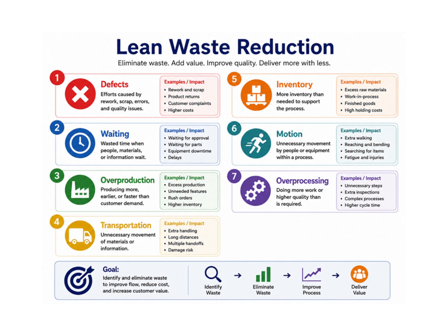However, once an organization begins improving a process, it often discovers additional forms of waste that increase cost, slow production, and reduce efficiency. This is where lean principles become important. For example, in the bottle cap process, defects occur when caps are too loose or too tight, leading to scrap, rework, or customer complaints. Waiting may occur if machines break down or operators wait for adjustments. Overproduction could happen if defective bottles continue being produced before the problem is detected.